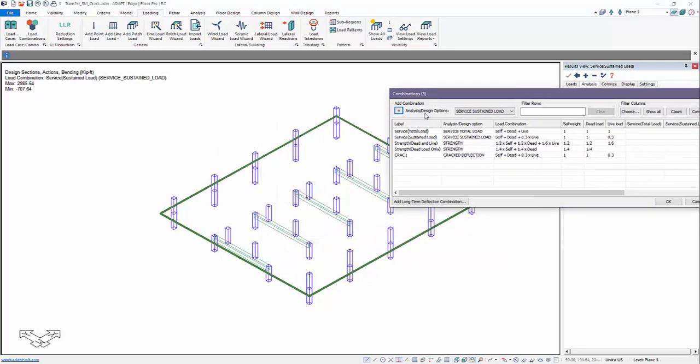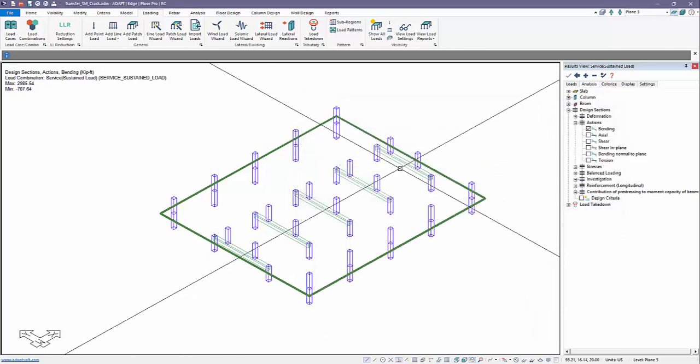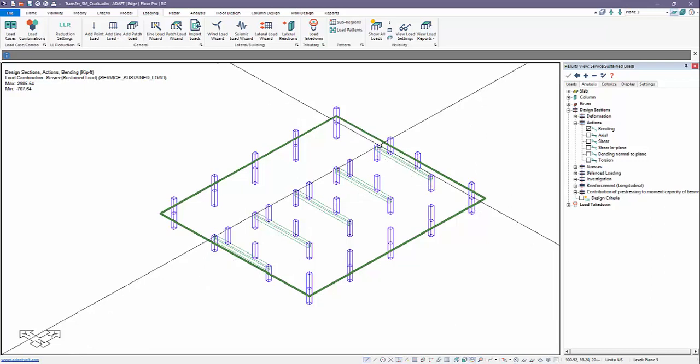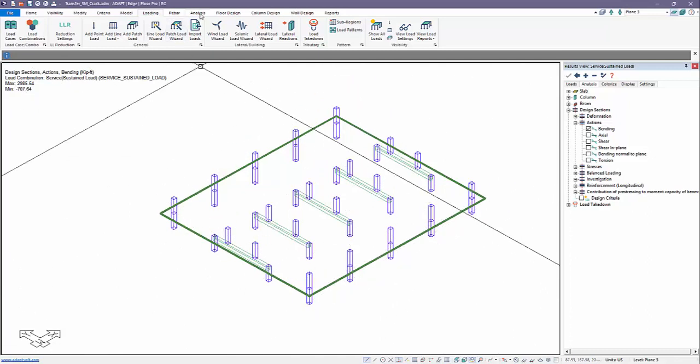So we want the program to determine the level of cracking, if any, at these beams with the application of the reactions, participating in the loads that might produce moments that exceed the cracking moment for the different nodes in the structure. So we have already obtained the reactions for tributary and for the global FEM run. We're going to create a baseline solution, which means we're just going to solve this particular level without any reactions, just to see where we're at in terms of the cracking of the beams with the load applied only at this level. So let's go ahead and start.